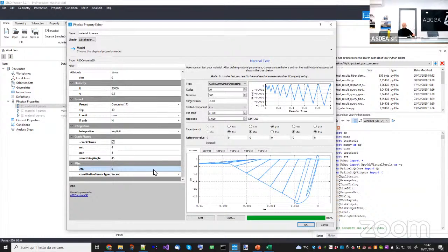Okay, so the viscosity of concrete, and for example, this is useful if you are doing dynamic analysis with a fast loading rate and you want to have the effect of the concrete stiffening due to a higher loading rate, you can apply the viscosity parameter. Now, just to tell you what's going on, if you put a viscosity parameter which is less than the typical time step, which now is a total duration of 1 second divided by 1000 steps, which is 100 per 10 cycles. So if I put a value which is significantly smaller, like instead of 1 to the minus 3, I put 1 to the minus 5, you will not see anything here. But if I start increasing this one, it will be more evident.